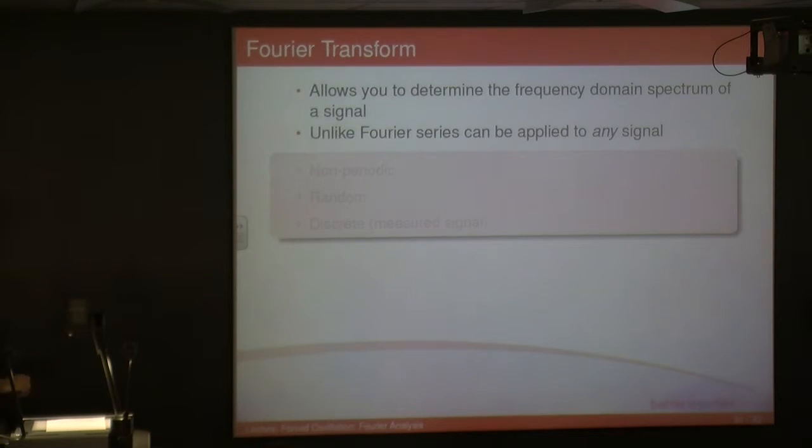The Fourier transform is a certain type of Fourier series in a sense. Well, I lie. A Fourier series is a certain type of Fourier transform. And a Fourier transform allows you to deal with a time domain signal that's of a different form. In fact, any signal. It could be non-periodic, it could be a random signal, or it could be discrete, a measured signal. So say like I said, you've got your component, you're testing it on a shaking table, you've attached an accelerometer to that object to measure the acceleration forces. Obviously, that will give you a time domain response,